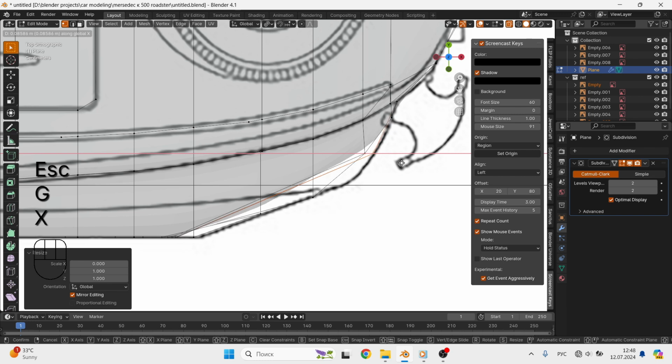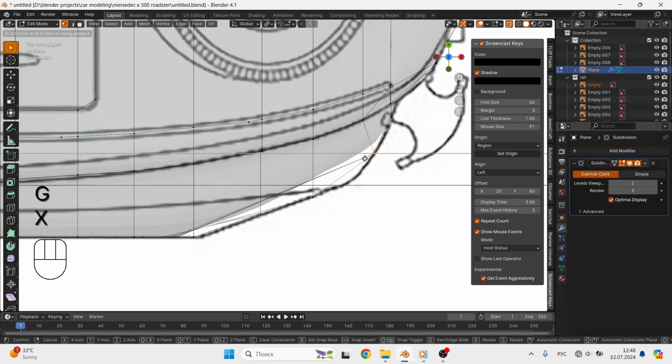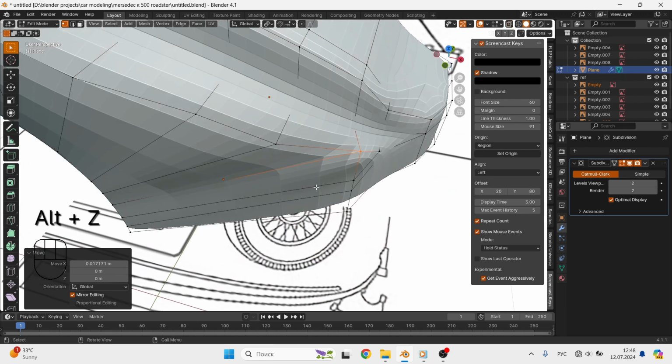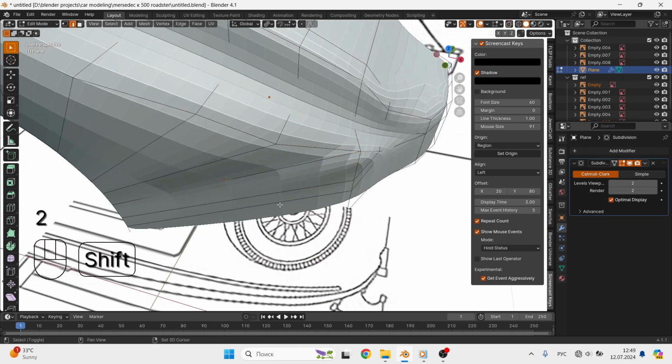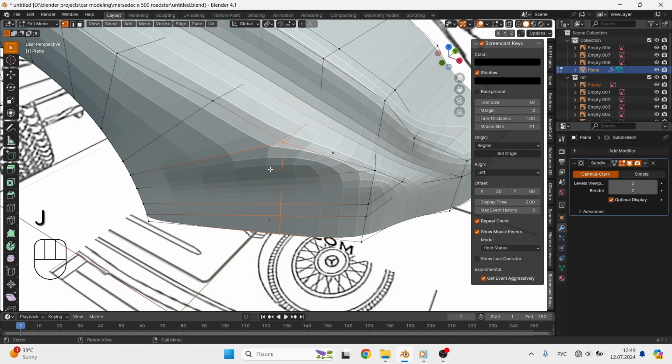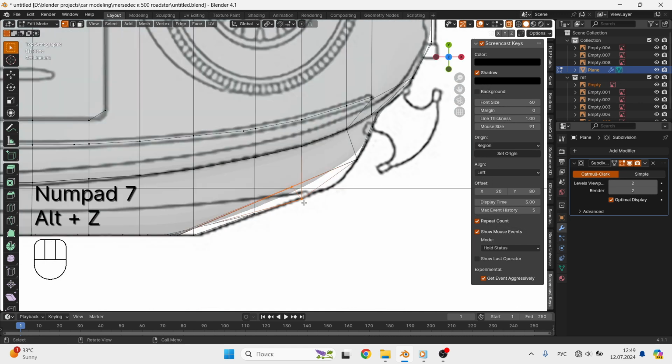Wireframe modifier. The wireframe modifier transforms a mesh into a wireframe by iterating over its faces, collecting all edges and turning those edges into 4-sided polygons. Be aware of the fact that your mesh needs to have faces to be wireframed. You can define the thickness, the material and several other parameters of the generated wireframe dynamically via the given modifier options.